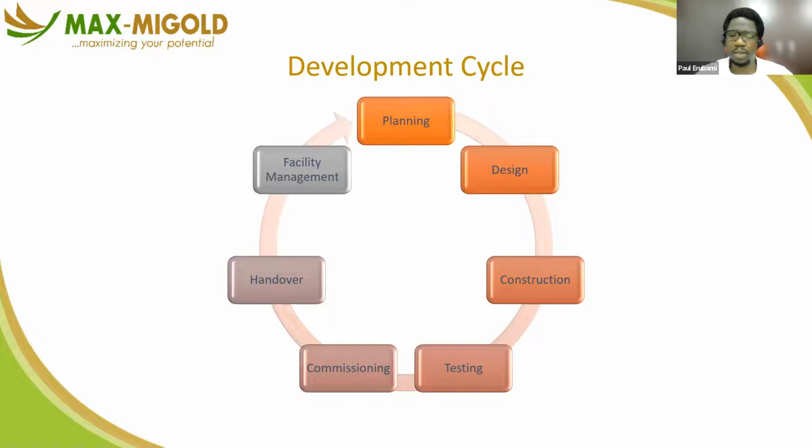Of course, you've done your testing. The structural testing shows that the stairwell is strong enough. The structure is strong enough to hold 500 people by design requirements. But that's testing. For commissioning, you need to have those 500 people actually run or walk through the stairs, and the stairs still stand and nobody gets injured. Nobody complains about fainting because of the crowd. And those are the kind of data you have to accumulate and record to show that the stairwell, even though it is structurally tested okay, is adequate, commissioned for 500 people, maybe 5 stories and 100 evacuating at every floor.